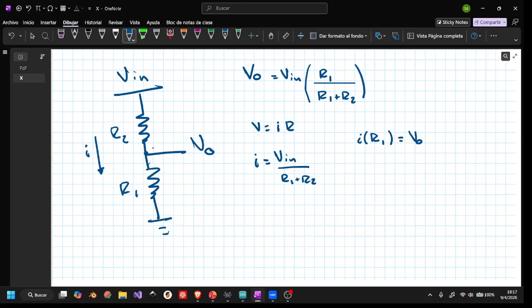Okay, these two resistors are connected in series, right? So all the voltage across this big resistor generates this current. That's this formula, the one here. The second formula is just taking this part, because this is not connected to anything, so all the current is here. So now the current flowing across the resistor R1 is the same current. I generates now this voltage, the voltage here. And I can substitute this in this one.